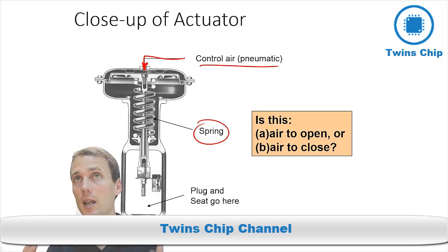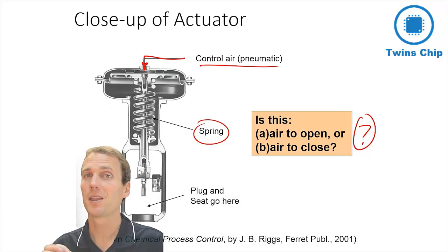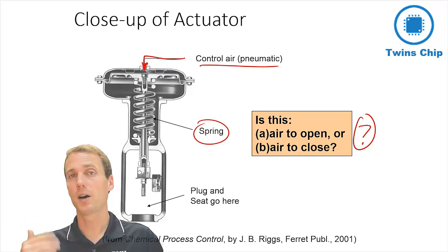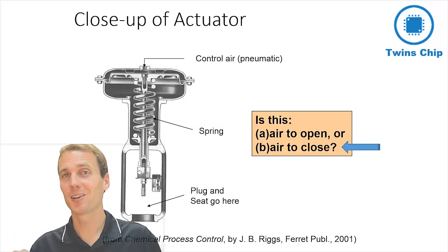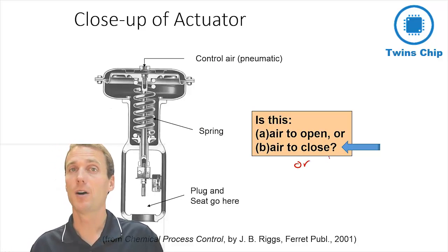So is this an air to open or air to close valve? Just think about that for a second. If I apply air pressure, does it open the valve or close the valve? And is it going to fail open or fail close? So you probably got it right. This one is an air to close or fail open type valve.